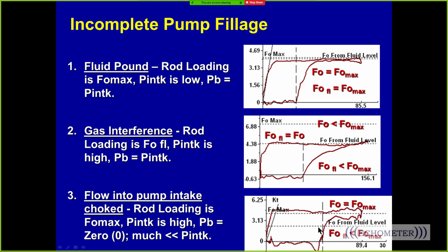Well, the fluid comes from slippage. So this pump displacement, this stroke right here, is from slippage between the plunger and the barrel. And they typically will be consistent because every stroke you'll see the same amount of slippage. And so if you were to overlay many strokes with a blocked intake card, they should all match up and be almost identical. The other thing is the fluid level FO line is going to be much lower than FO max, and it doesn't match up with the pump card. So there's something not quite right here. There's something wrong when you see this. Well, it's a blocked intake.